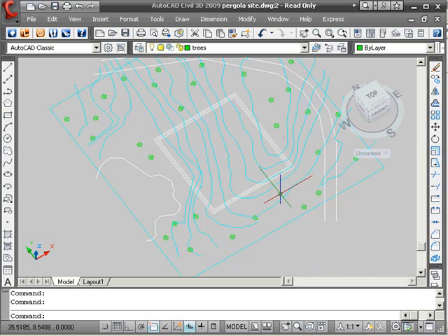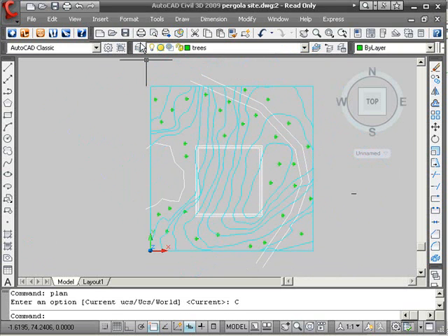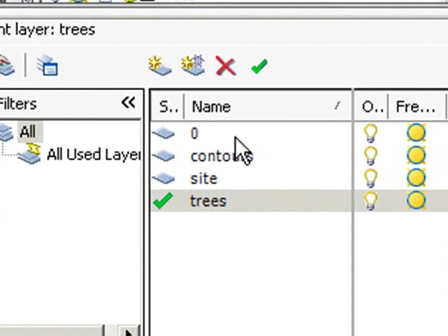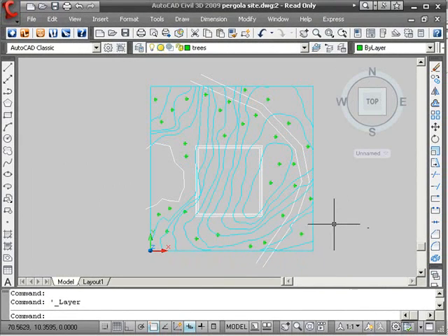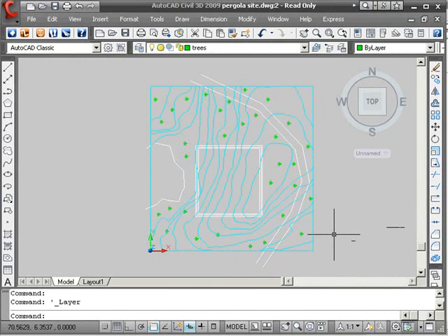We also have some site features like road path and some data which we want to have as basic data with SketchUp. And here we could see that we have the layers. We simplified the layers in AutoCAD. This is very important. We don't want to take everything with us, so here we could see just simple layers. And also we tried to study the scale of the drawing. It should be the same environment as in SketchUp. We also try to make sure that we use the 000 as a reference point when we work in AutoCAD.